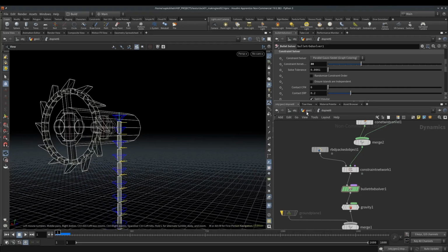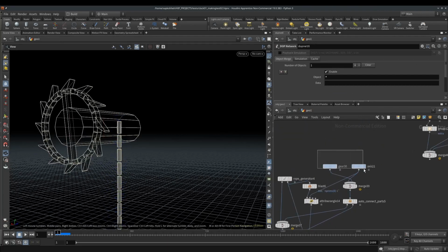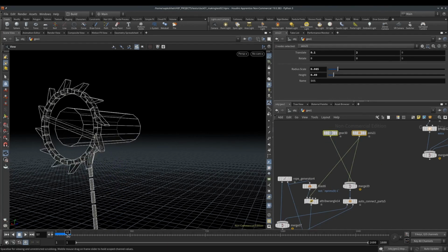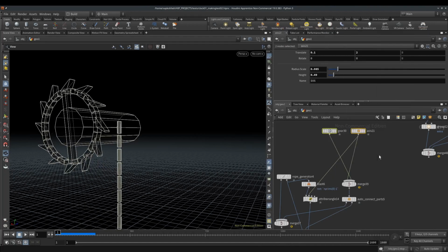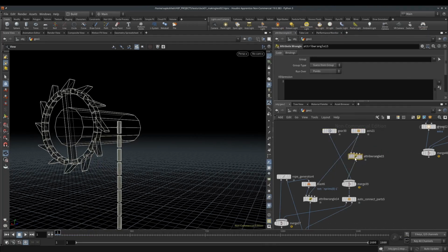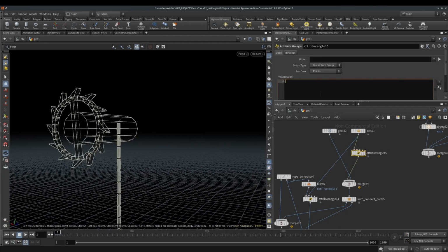Now, before we connect the pallet back in, let's actually wind this thing. So to wind, we will just animate this axis. We will use the active and animated attributes for the axis to say for 100 frames we will wind it up, and then for 50 frames more we will let it sit there and relax, and then it can start going. So active will be equal to frame greater than 150, and animated equals not active.